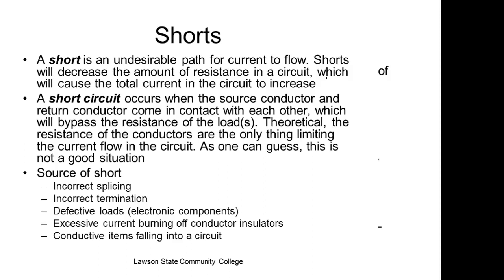So a short is undesired current flowing, it's just that we've lost control of the current. It's an undesirable path for current flow. Shorts will always cause the total resistance in the circuit to go down. If the total resistance goes down, then the total current will go up, right? You understand that? Always. So we can have a short without a short circuit. So what's a short circuit?